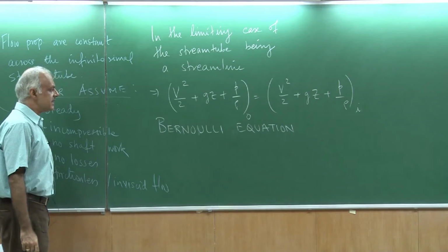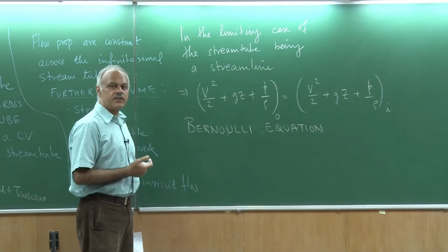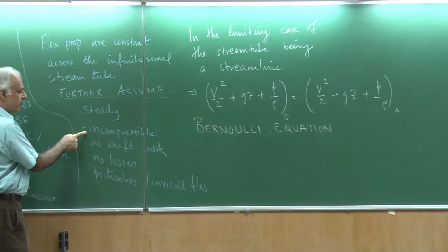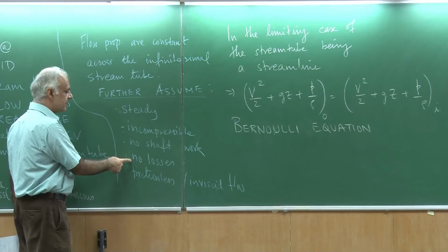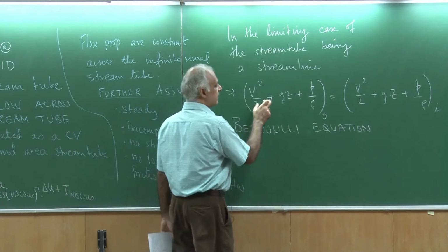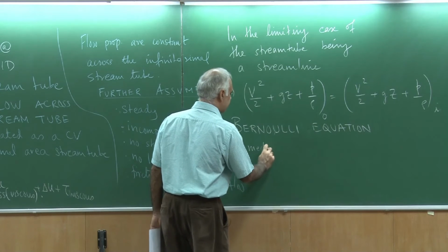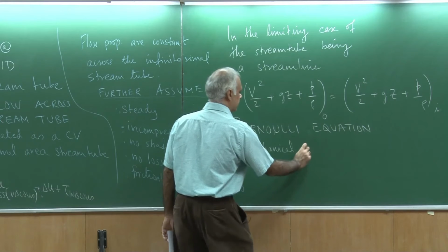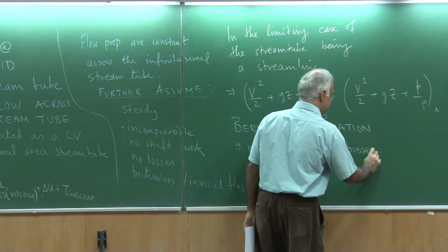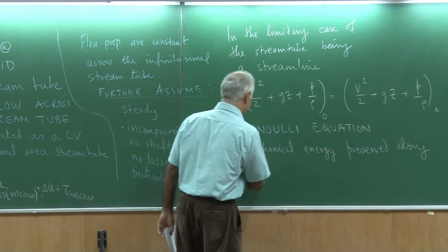So, the Bernoulli equation says that along a streamline for a steady incompressible, inviscid flow, which has no losses and which has no shaft work, I have the preservation of the mechanical energy. So, this implies mechanical energy is preserved along a streamline.